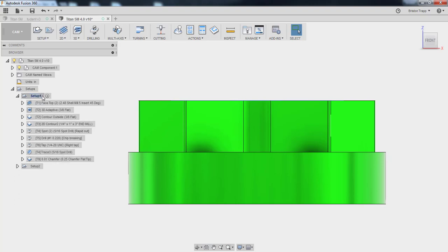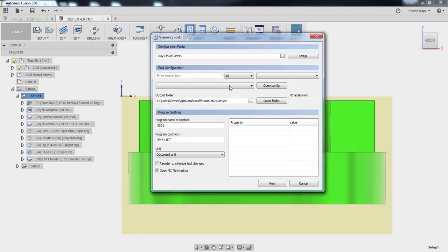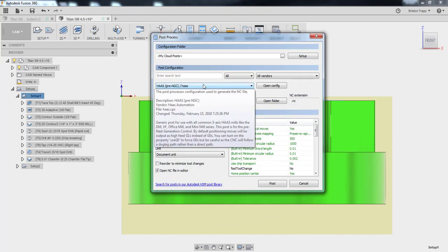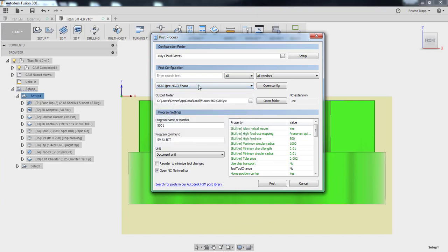and tool number 9 is our chamfer. When you go to post-process, make sure you post-process either on the pre-next generation control, which I do believe works on both mills. But if you're going to use the next generation post processor for the super mini mill, make sure you actually use the super mini mill, because if you use the regular mini mill, this post processor will generate a feed rate of 650 inches a minute, and it will result in an over feed rate error.